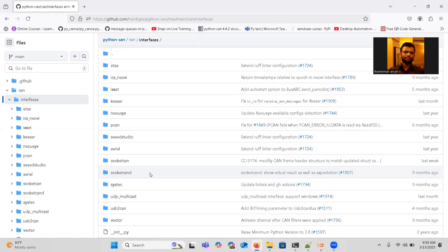So when the network analysis tool vendor has some sort of GUI, why do we have to look for Python CAN? It is needed because Python has a lot of pre-written libraries, and the system testing engineer can come up with a customized solution for their need. When you have to work with CANoe or other GUI tools, which are available from different vendors, it needs a learning curve.